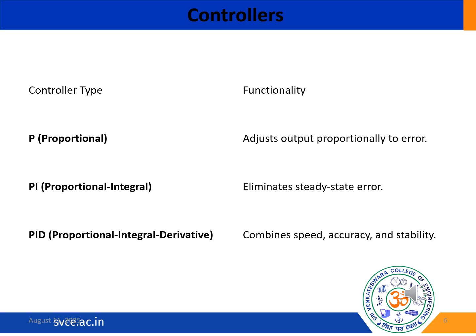So in these types of systems, we use some tuning methods. I'll just tell you what the tuning methods are that we are going to use for these particular systems. Ziegler-Nichols is the first type of tuning method. This particular method is an empirical method using system response.